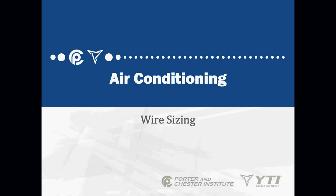Okay? I don't want us to run a 100 amp air conditioner off of a wire that is only rated for 20 amps. Okay, bad things are going to happen. And it may not necessarily blow the breaker, it might melt the wire down, might melt the conductor down. When you have a breaker panel in a house and you have wire that's sized for a maximum of 20 amps and you have a breaker that's blowing, do you increase the size of the breaker so it doesn't blow anymore?